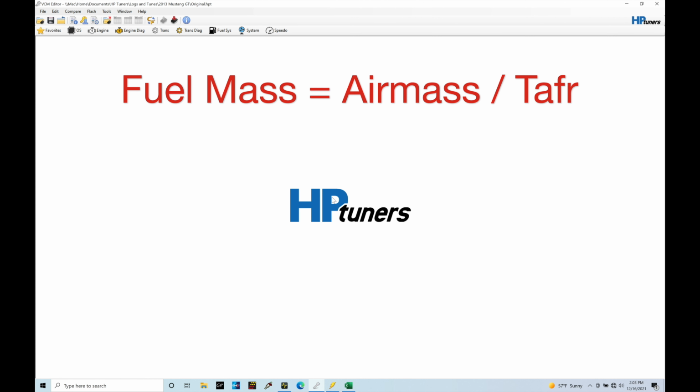In fact, it's one of the most important things that we're going to have to set and make sure is accurate. I'm going to have another video on spotting bad injector data, what we can look for and some trends we can take a look at. But for right now, we just need to understand that proper injector data is critical. So whether you're installing Ford Racing performance injectors or Injector Dynamics injectors, we want to stick to something that has proven data that we know works, that's not going to introduce bad data or a fueling error, which will just make your life pretty miserable trying to sort it out. So we always want to start off with an injector that has known data.